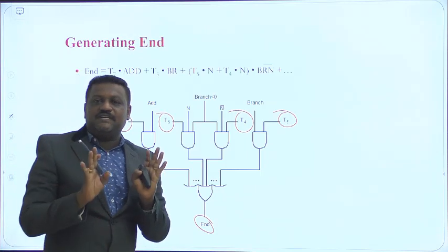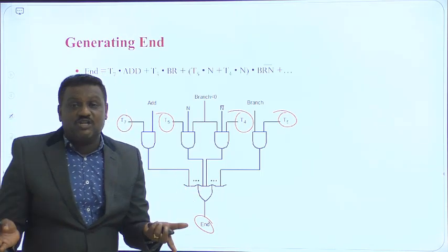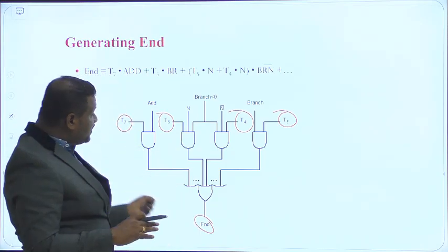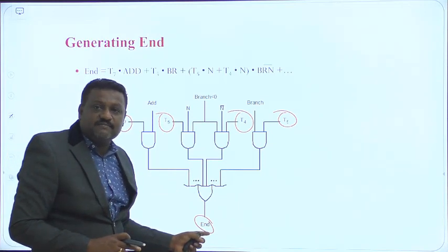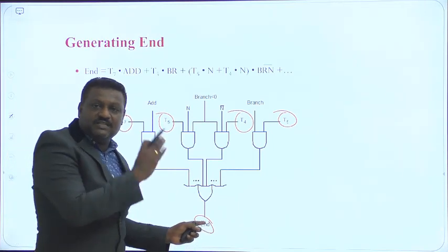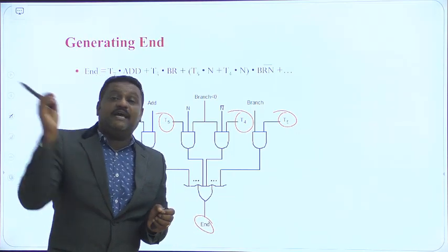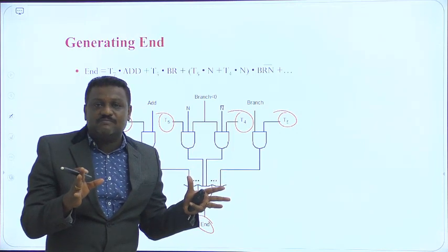So here it is very clear, friends, that the hardwired control unit is a combinational logic circuit, and it consists of a number of such circuits for generation of control signals. Observing this whole thing, the control signals are generated by the encoder circuit by considering different inputs.